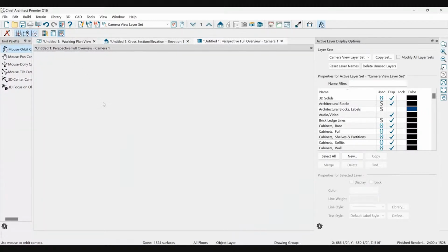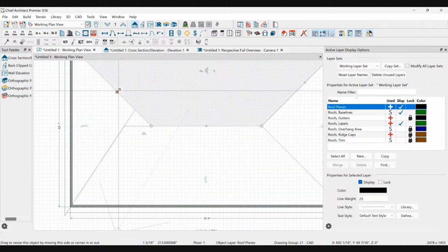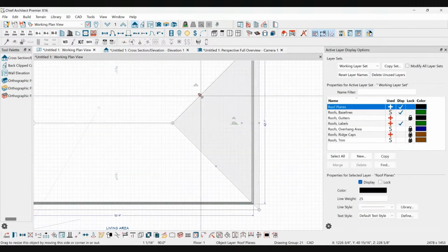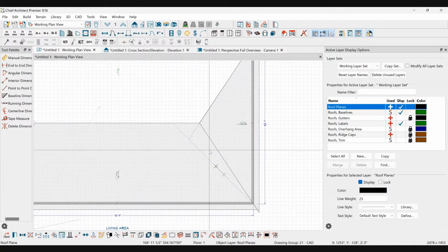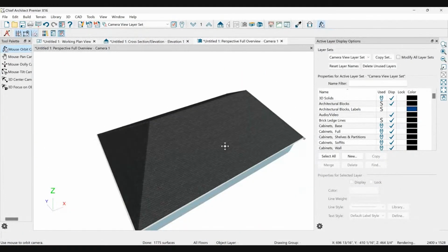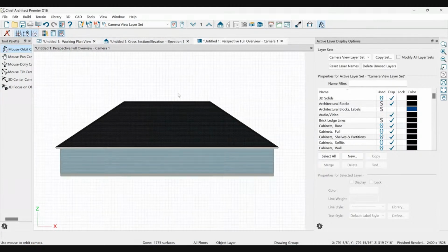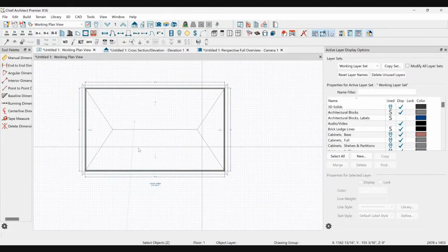And so what you're going to do is use the join roof planes command, and rejoin all these edges to each other. Oops, come on. There we go. And then it's going to be corrected. All right, so there we go. That's good. If we go to our elevation view, look at that. Now the house looks a little steeper on the side. It's just going to look a little grander, right? And so that's frequently a strategy people like to do.